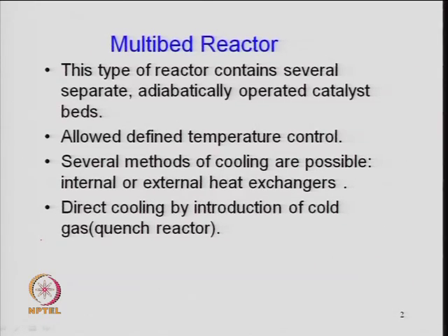That is easy to handle in one way, and it can be used when the reactor is operating under isothermal condition. Isothermal means there are no temperature gradients prevailing in the reactor. When you pack the reactor with solid material, which is a catalyst, then hot spot formation when the reaction is exothermic is a big issue.